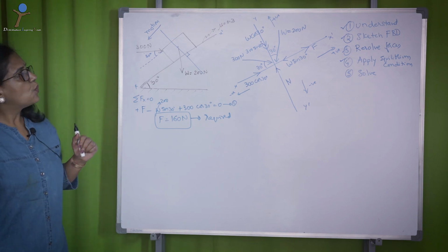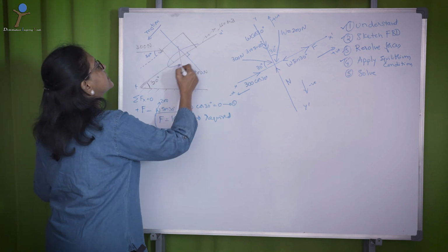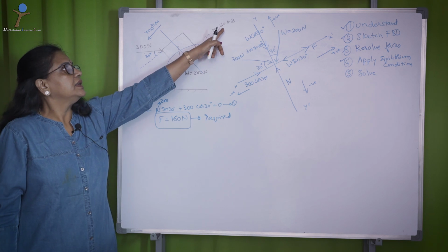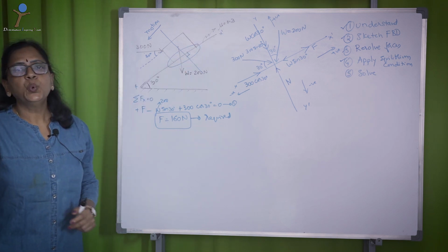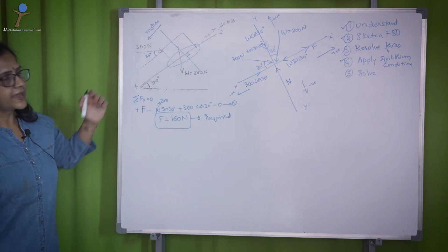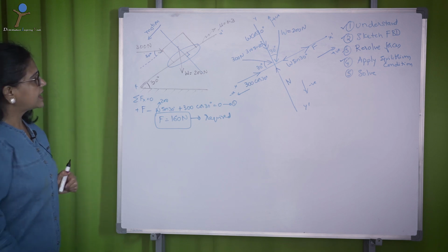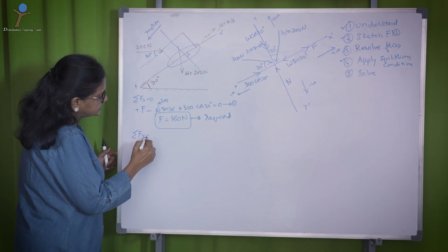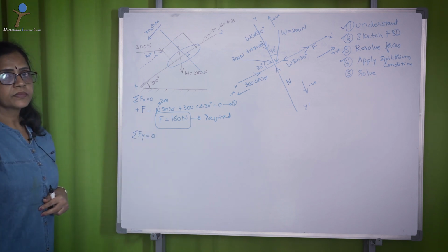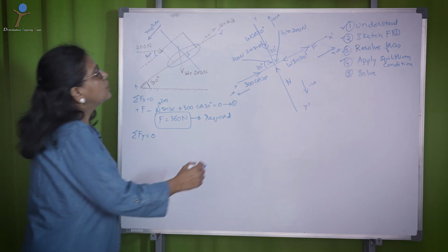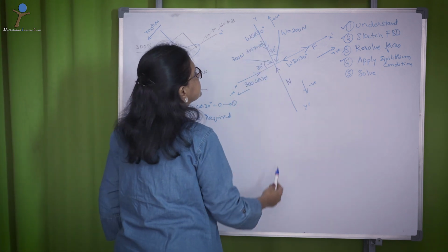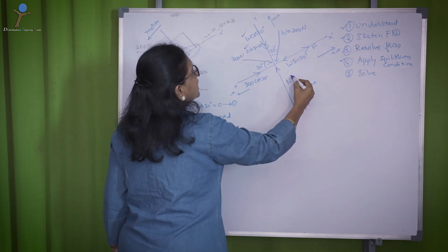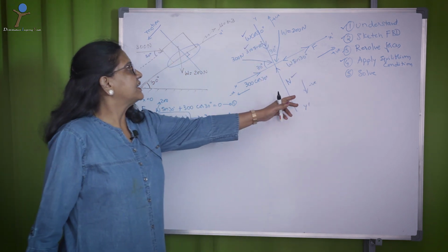Now, you should know what is the actual resistance existing at the contact surface, which depends on mu of the contact surface. To get that, you take the next equilibrium condition, sigma Fy equal to 0. In sigma Fy equal to 0, look at the forces acting on the y-axis. One is W cos 30, 300 sin 30 and N. Now, follow the sign convention.